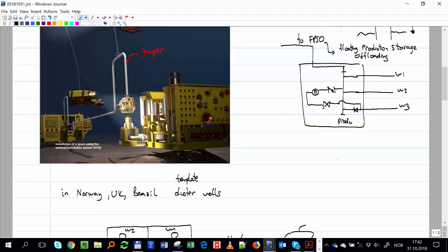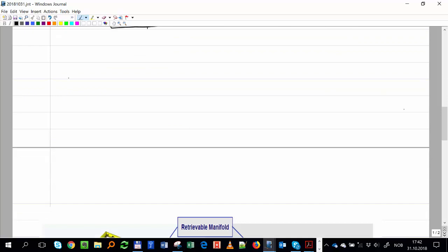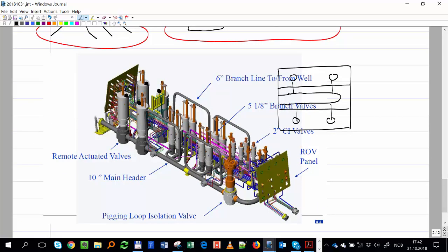And if you have just a straight pipe, what could happen? If you have a pipe that is connected to another pipe here, when this goes up, it's going to break it. Or it goes down, or you have fatigue, up and down, and it's going to break eventually. So that's why we have this strange shape, to give flexibility to the system. When it goes up, it's like a spring, like a coil.